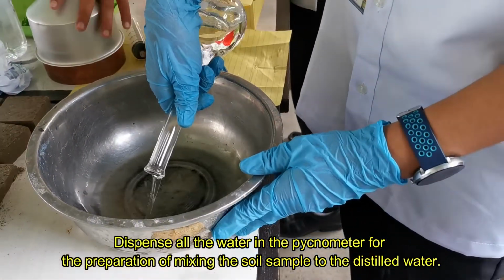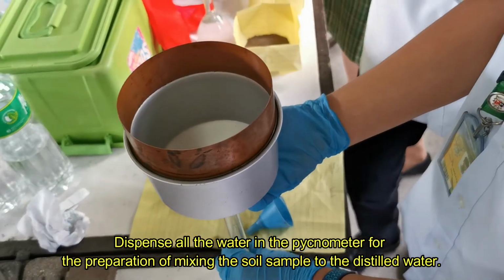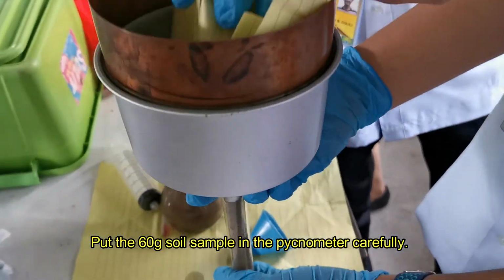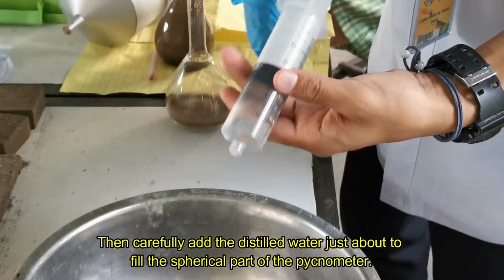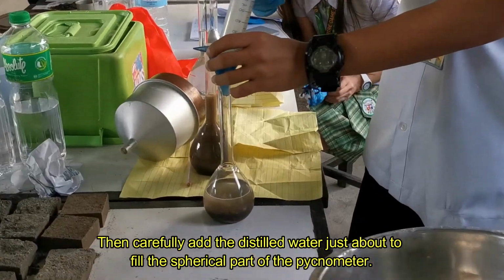Dispense all the water in the pycnometer in preparation for mixing the soil sample with the distilled water. Put the 60 grams soil sample in the pycnometer carefully. Utilize a big funnel for easy transfer of the soil to the pycnometer. Then carefully add the distilled water just enough to fill the spherical part of the pycnometer.